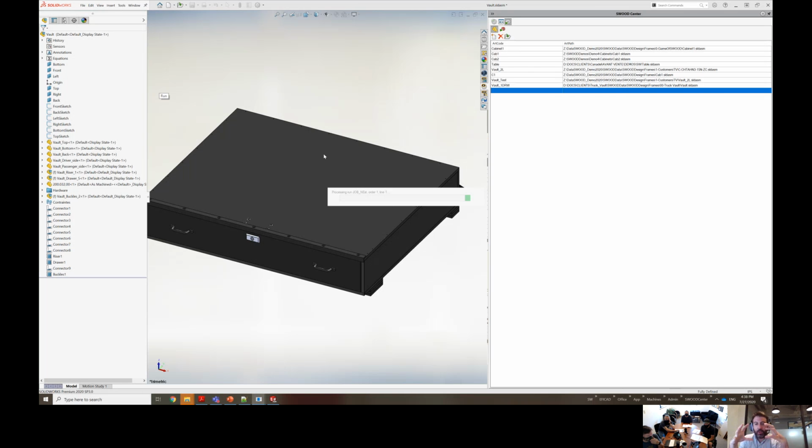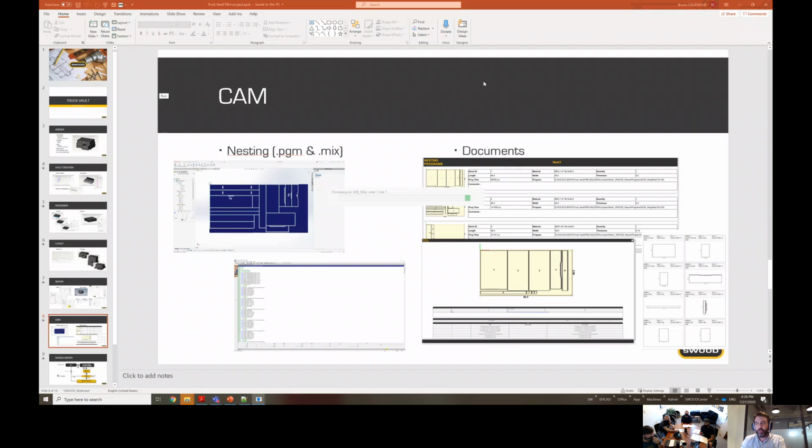But the drawing, if you create the drawing with the frame you have in your library, every time you insert your frame in a multi-level project, or every time you copy to create a specific project, we'll be able at the same time to duplicate the drawing. And of course, all the changes you will do in the assembly will be populated in the drawing like any SolidWorks file.